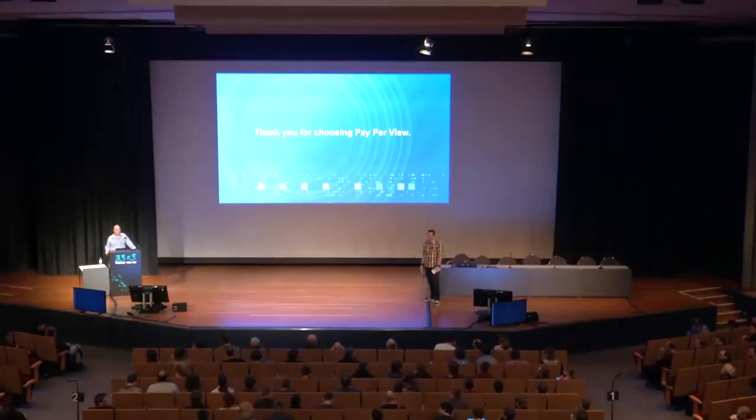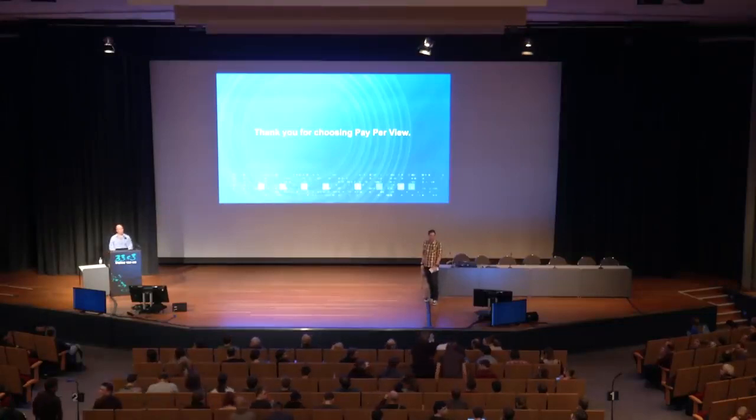Thanks very much for the lecture and well done on all the work. My question is, how does the glitching attack work? For the glitcher, it was quite simple. I dropped the voltage for a very brief period of time, and it's enough time that it causes at least one instruction to not execute properly, but it's too short of a time to cause the chip to reset. So essentially, I'm corrupting one instruction.